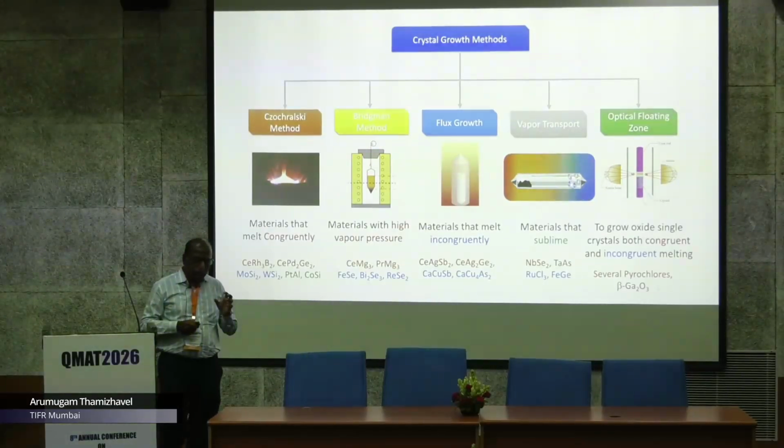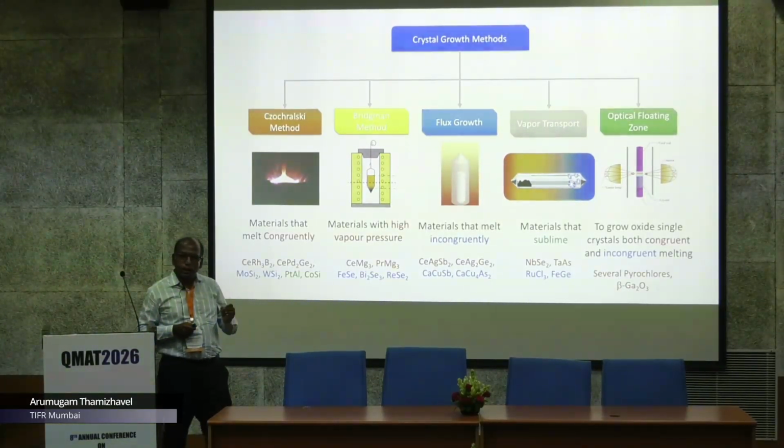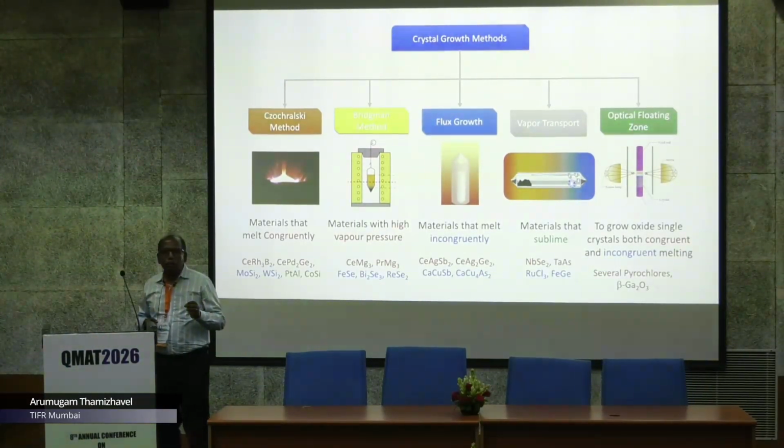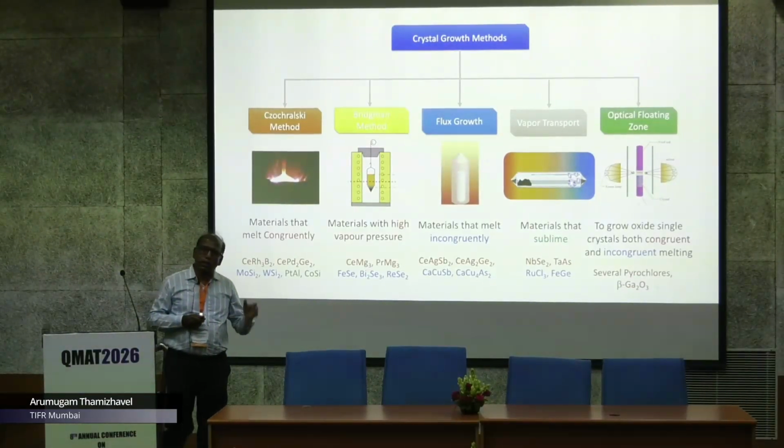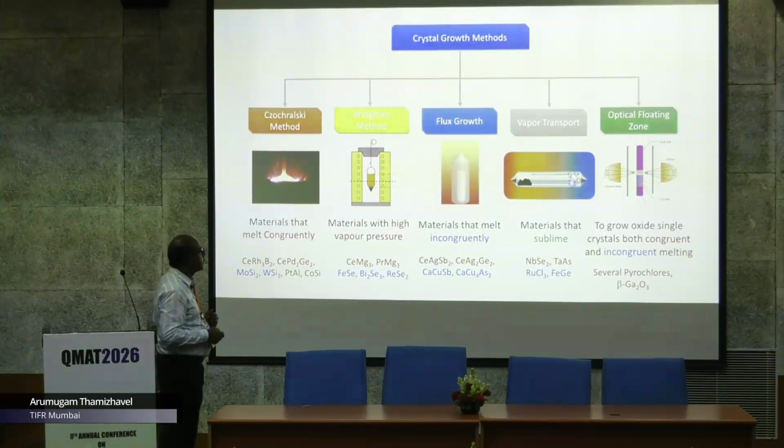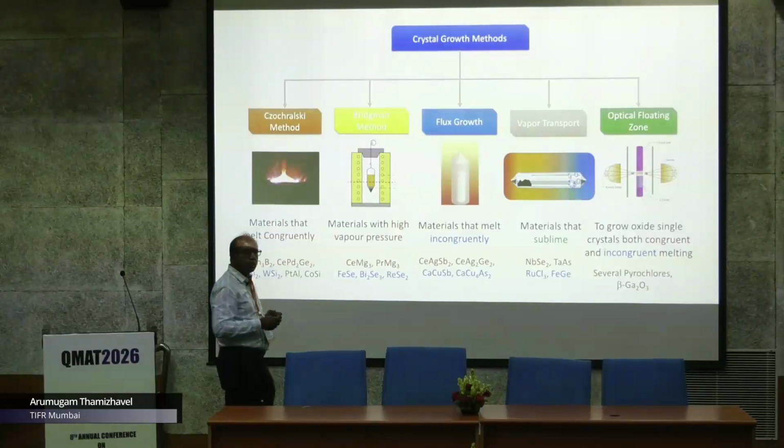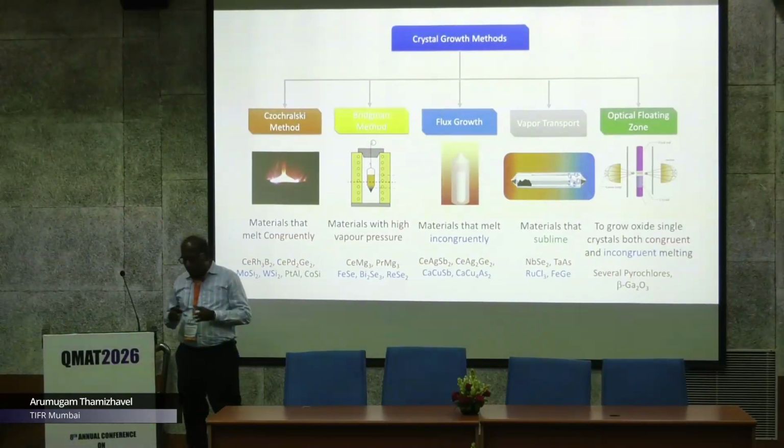In this case, the entire chunk will not be a single crystal. You will get large grains of the single crystals. And we do Laue diffraction to find out the orientation of the crystal, and we cut the crystal for the anisotropic studies.